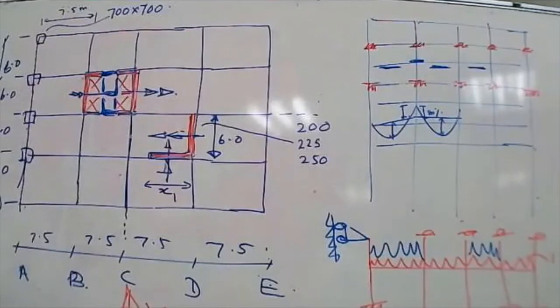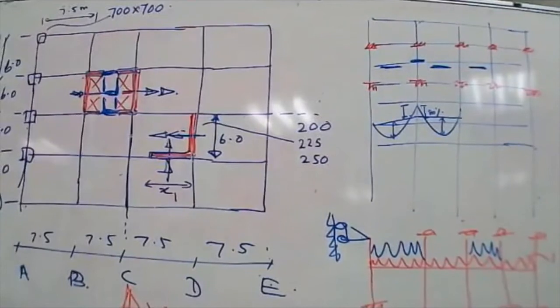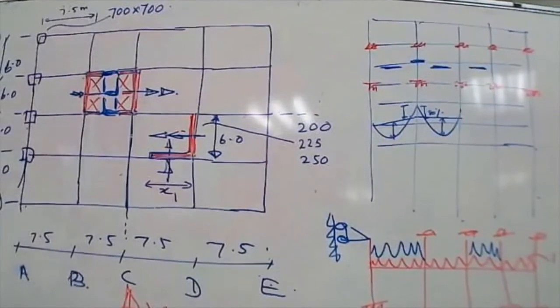Actually, even if you have different sections, when you are calculating the bending moment values, this variable section is already taken into account. This is organized by the computer program with different beam sizes. So even if there are different beam sizes, there's no harm in doing moment redistribution. But I might stay somewhere around 15%, rather than going for something like 20 or 25%,